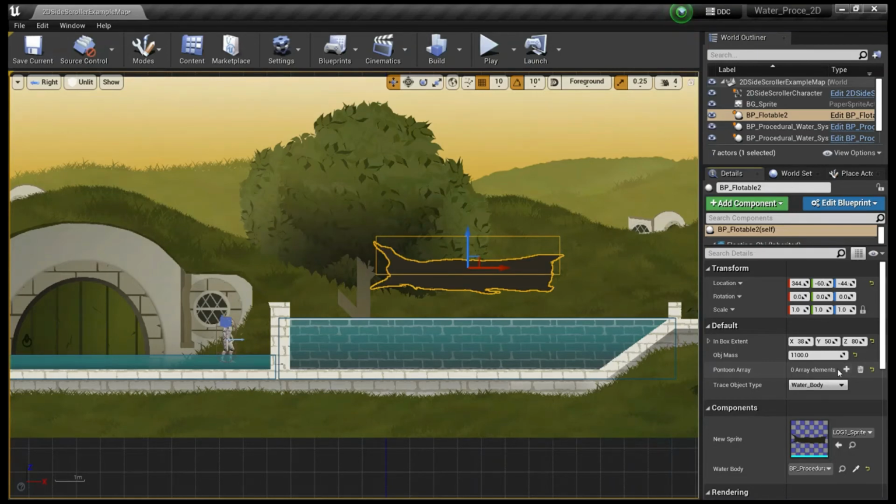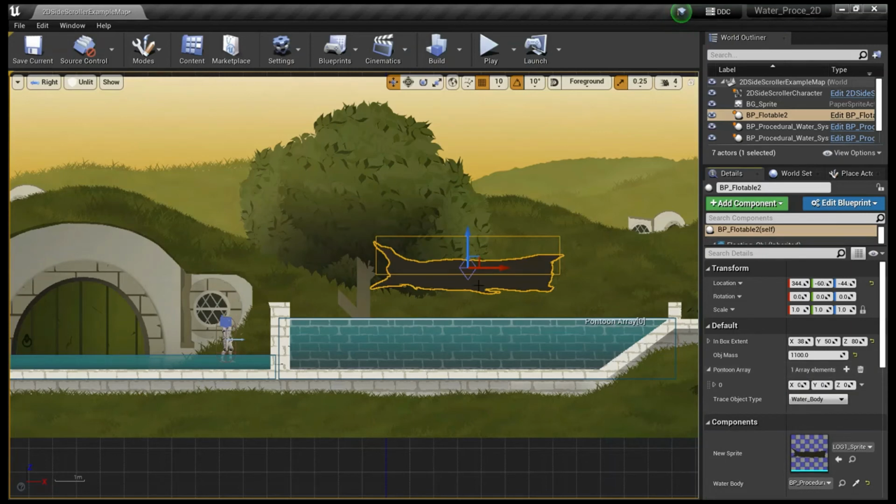Out of the box, at least one pontoon will be available, at the 0,0,0 position, and these are relative positions. Keep in mind that these are relative positions. If you need to change anything, these relative positions are converted into world positions inside the buoyancy logic. But keep in mind these are relative positions, and these are really easy to set up.